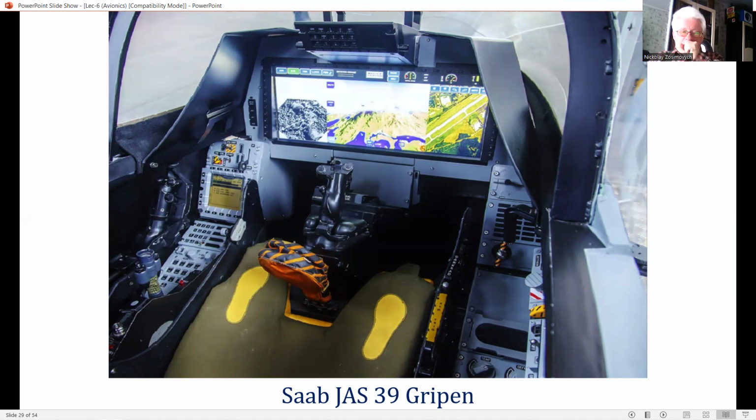PIOs were in fact encountered in early development flight testing on the Lockheed YF-22 fighter and the prototype Saab JAS-39 Gripen fighter, and also during early flight testing of the C-17 transport and Boeing 777. These have been attributed to rate limiting effects.